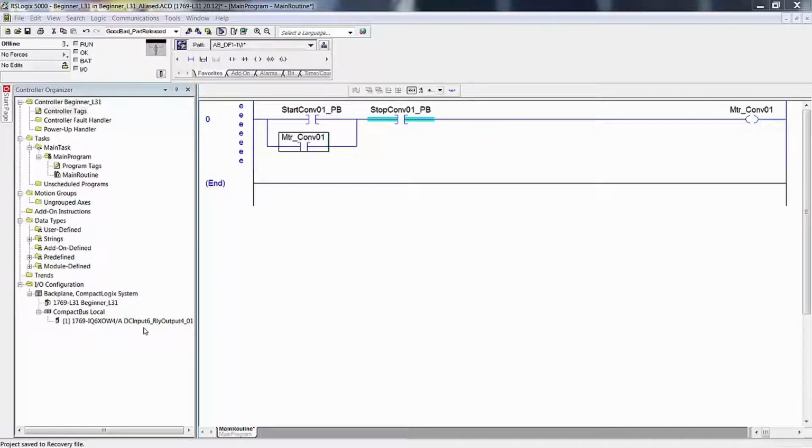Meaning when you first started, if you were aliasing these push buttons right now to actual I/O input points that are going to be wired to actual field input devices, push buttons, and you went through the whole process, let's say you had 15 conveyors. And so you wanted to keep everything for conveyor 1 in one location, contiguous tags, etc. Let's say you get all the way done, you've got it all assigned, and then you're working with it, you go, oh, I forgot something. You forgot one tag for each of the 15 conveyors. Well, if you've made them contiguous, meaning you didn't leave any space in between the I/O points, then you have no place to put them.